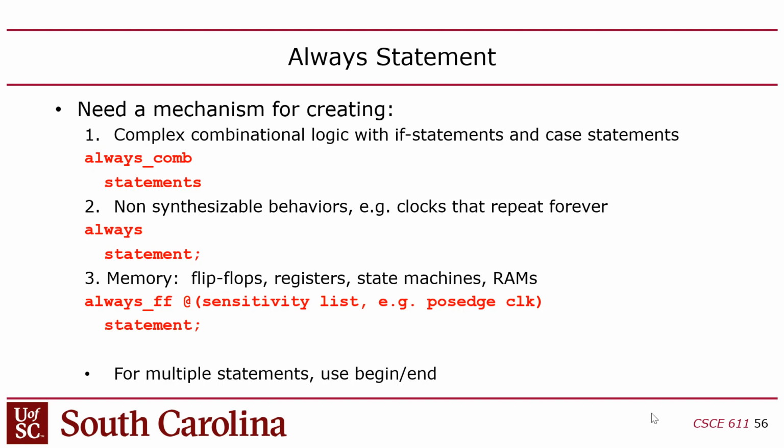Right? You guys with me? So, like you can say assign, and then you could do this trick where you say assign A, comma B. So technically, yeah, in this case, you're assigning A and B. But that's not super readable, right? With an always statement, you can have two lines of code inside the always statement that assigns A and B separately, right? That's the difference.